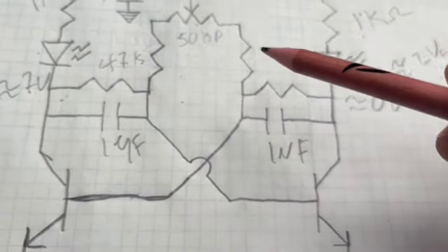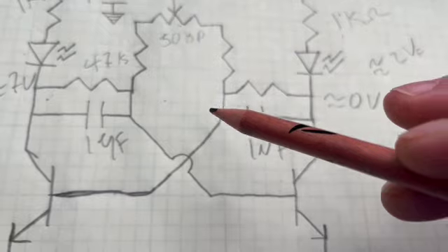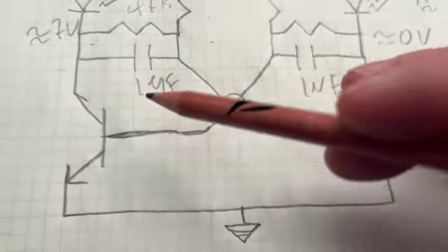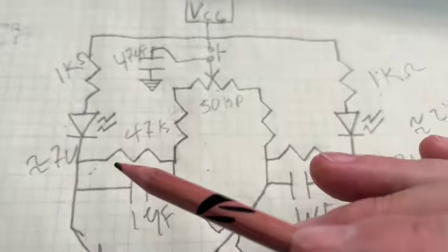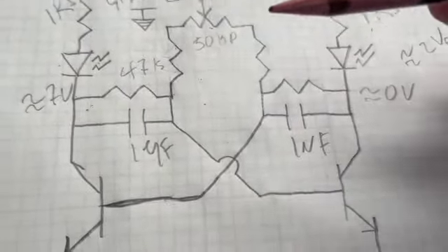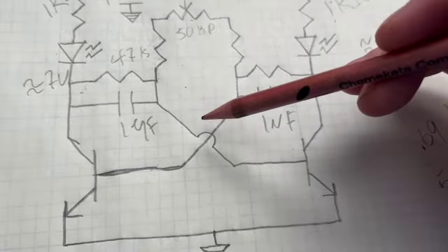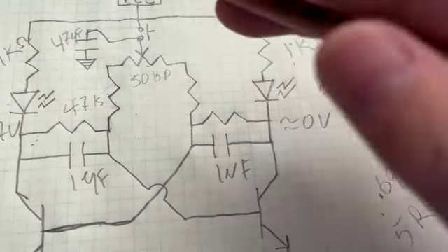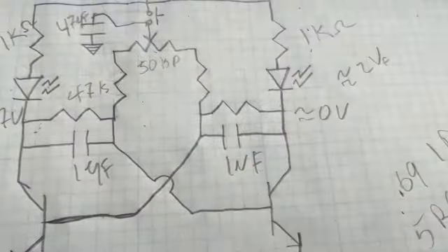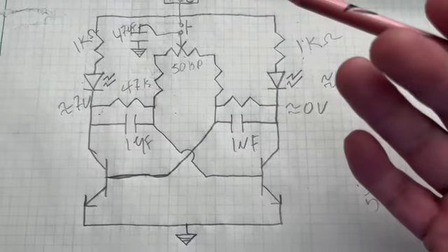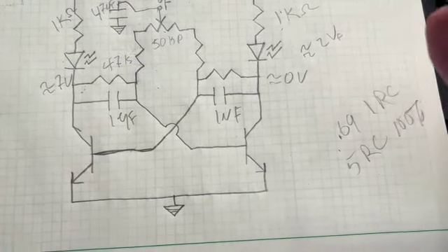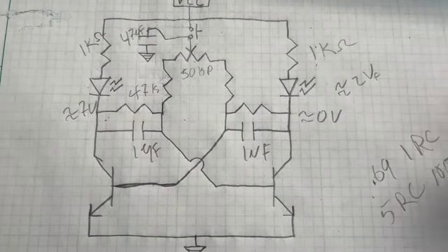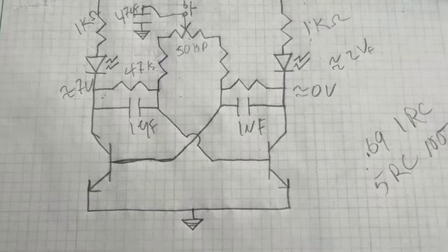So if you think about this being in parallel, there's not enough current going around to this side to activate this LED. So this one just stays off. And that's all there is to it. That's why when you let go of the button and the capacitor finishes charging, the oscillations stop. It's really that simple. We could put more into it, we could put more thought into it, but that is the plain and simple fact of the matter.